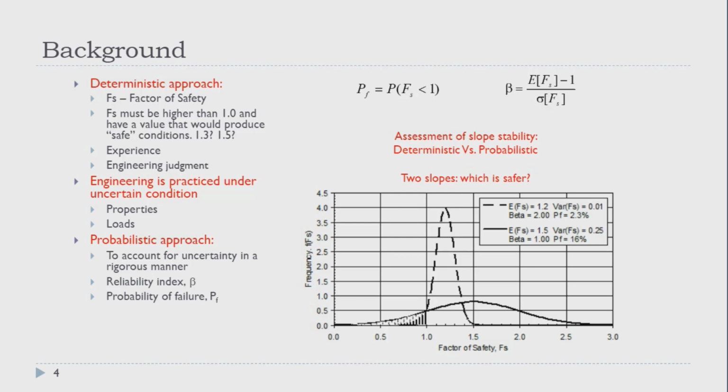So it deals with that uncertainty by establishing a minimal acceptable factor of safety. How do we know what is acceptable? Well, the design codes have established these values based on what seems to result in a frequency of unsatisfactory performance that falls within limits that we, as a society, can consider to be acceptable. That's basically how we work when we are doing a deterministic analysis.